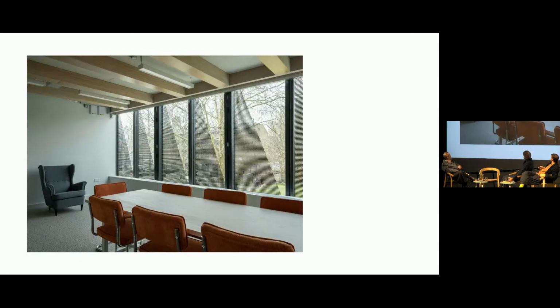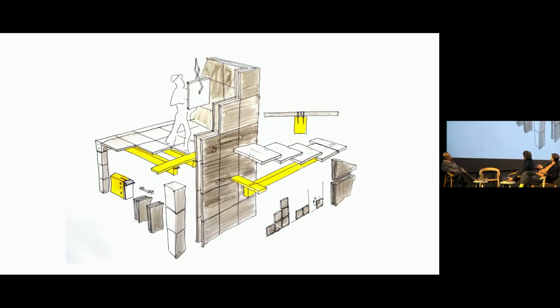Those structures are exposed inside the building. The windows are actuated, so they open at night, and the building cools down, and they close up in the daytime, and they keep the cold inside. So it's a very low carbon way to build. It's lightweight, it's quite quick, and it gets rid of air conditioning. So we're thinking the only issue with this is the concrete, and obviously we're working in stone. So the next step is, can we just replace the concrete with stone?